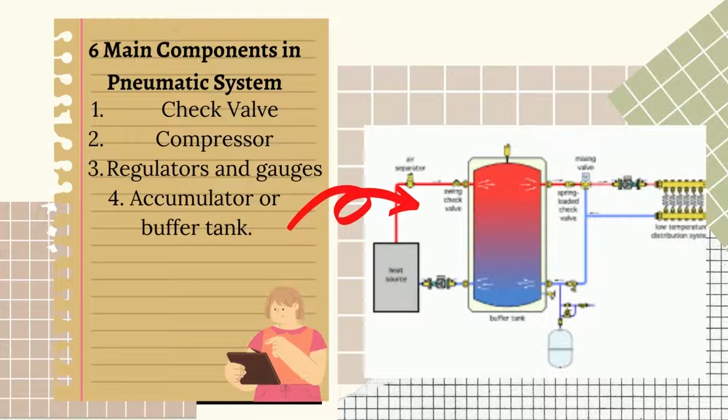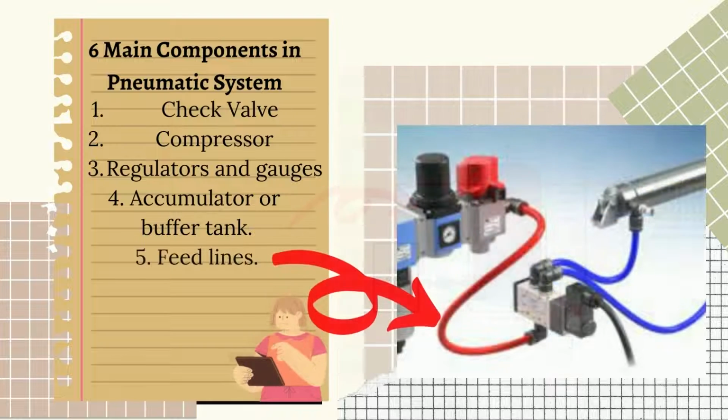This tank helps in preventing irregular airflow surges in the actuators, allowing the compressor cycle to maximize its shut-off timing. They also allow the compressor to be at the exact distance from the actuators in the project.